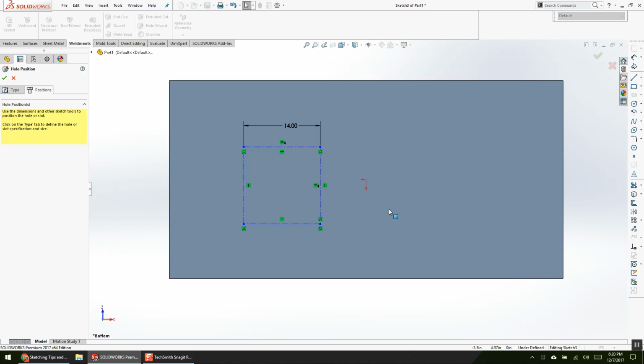So I'm pretty adamant on this because it boils down to separation of concern. When I'm modeling, my concern is that the 3D geometry is good, I have limited my liabilities, and it's readable and maintainable. A 2D drawing is a totally different discussion, a totally different separation of concern, and in 2D, my number 1 and only goal is to make the drawing as manufacturably friendly as possible. So I'm never going to compromise my 3D design because of a dimension I want on a print because the machinist needs that dimension. Right?